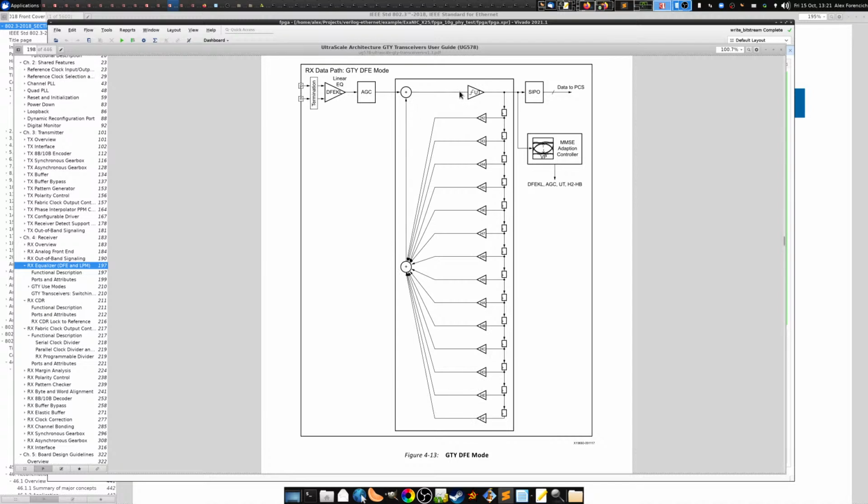So this has the effect of moving the sampling point around depending on the previous bits that we've seen. For example, if you get a bunch of 1 bits, then you should probably look a little bit higher for the next bit to detect the threshold more reliably. So that's kind of the point of DFE.